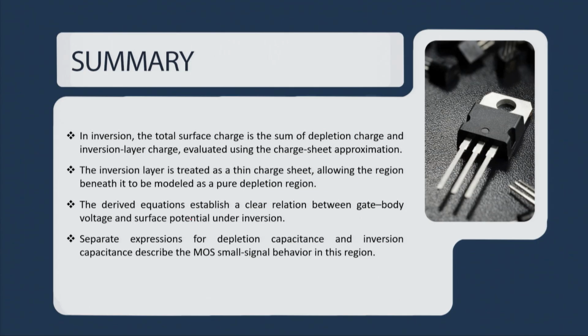We have seen that when you introduce a third terminal in a two terminal MOS, this third terminal will influence the inversion charge. Thus, we can use all the models we have derived for the two terminal MOS for the three terminal structure also, with replacement of N0 by N0 times e to the power of minus VCB divided by phi t, and the surface potential replaced by 2 phi f plus VCB.